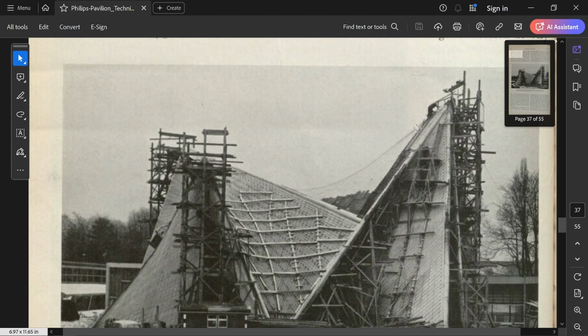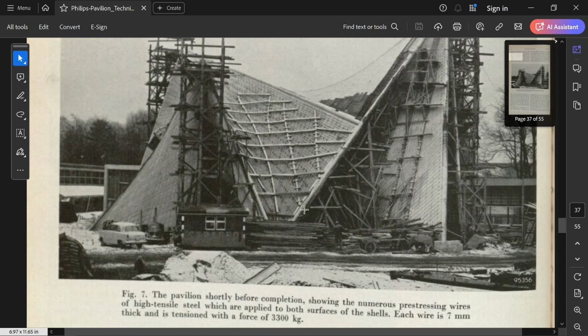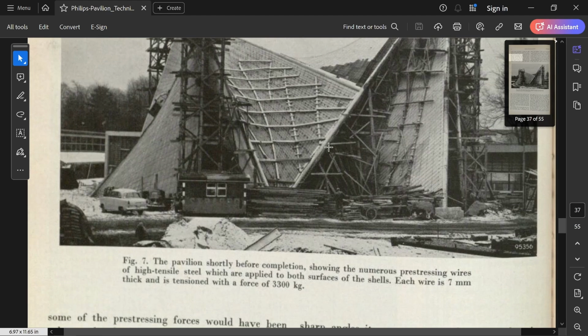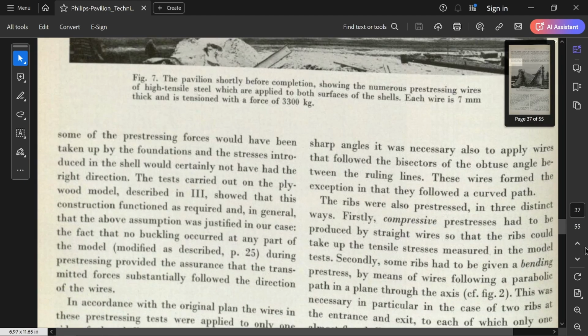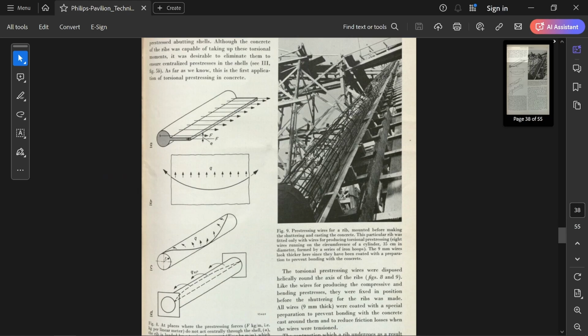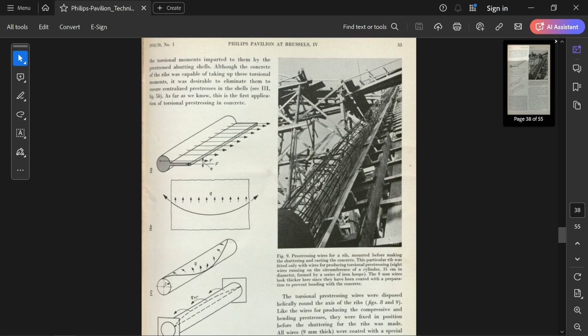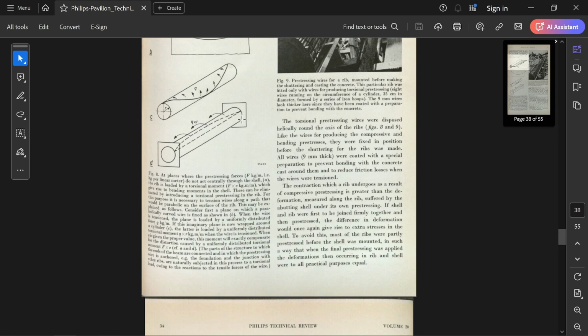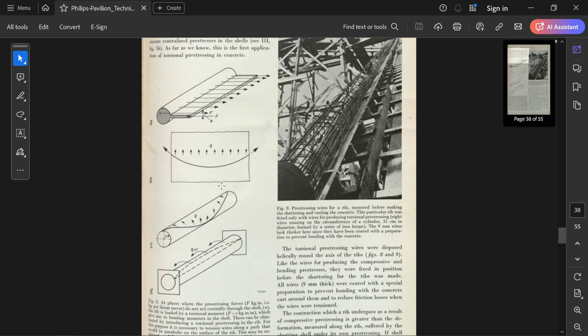See, those are the pre-tension rods right here, and they're both on the inside and the outside of the pavilion, anchored into these 40-centimeter frames, which are not pipe, they're concrete, pre-stressed concrete. And you'll see that on the next page. So this is the only concrete formwork they did on site, and it's also pre-stressed. And they pre-stressed the cables in multiple axes, not just straight.